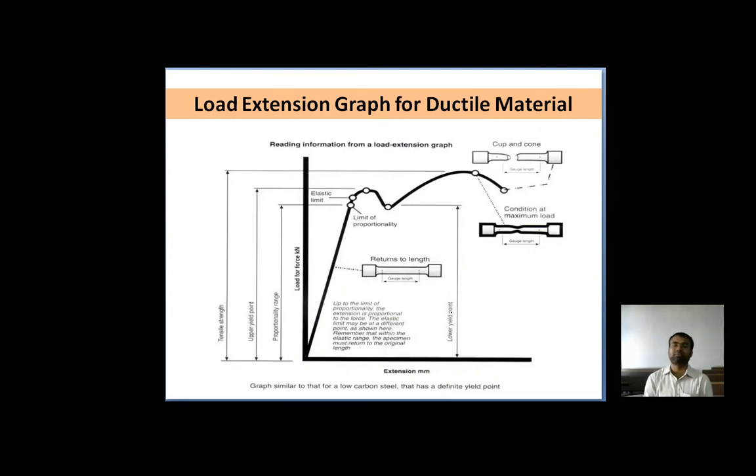Continuous elongation of that specimen occurs by propagation of the deformation region. That lowering of the yielding is called the Lüders band. It propagates along the gauge section, and only after the entire gauge section has been transformed by the band does the stress rise again.